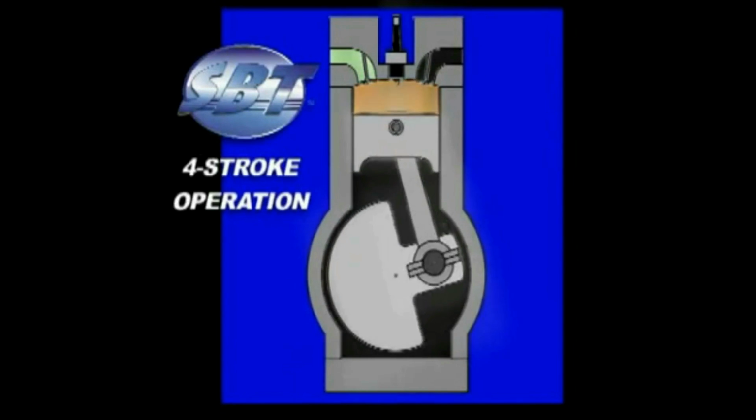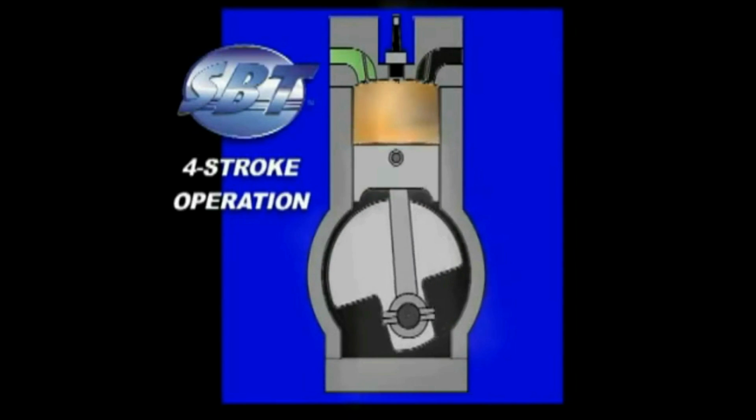The molecules of the gases inside the combustion chamber accelerate or increase in pressure, causing the molecules to collide with the sides of the walls with a greater force. This forces the piston downwards, turning the thermal energy directly into mechanical energy by decreasing the velocity of the molecules in exchange for increasing the velocity of the piston. This is called the power stroke and is the only stroke that powers the engine.